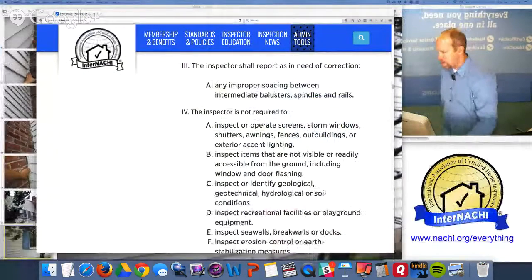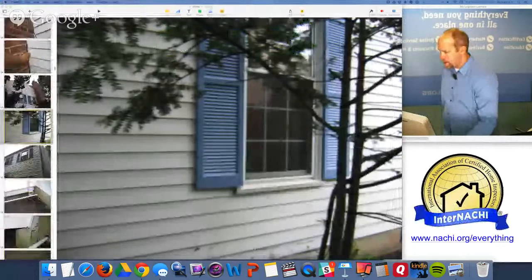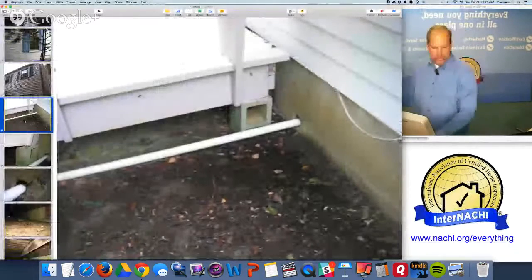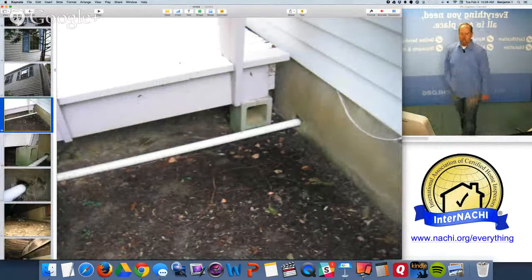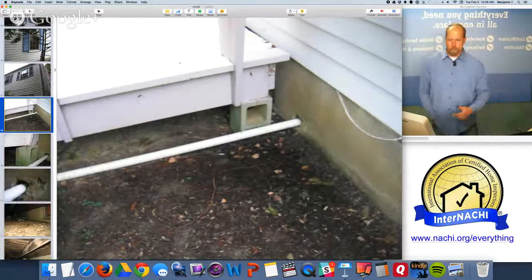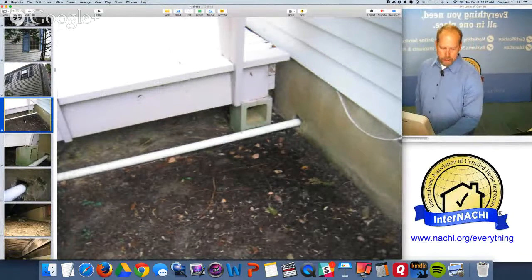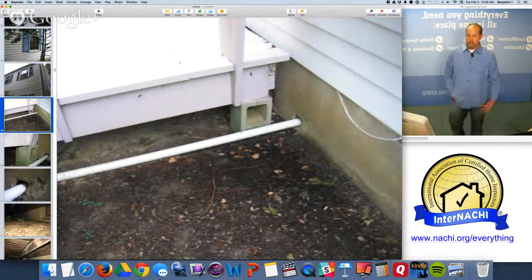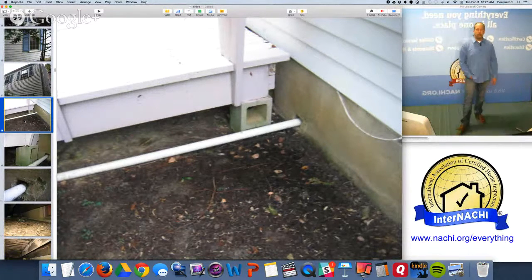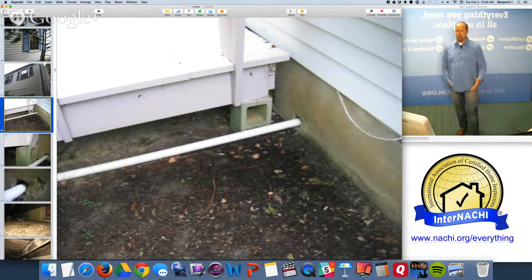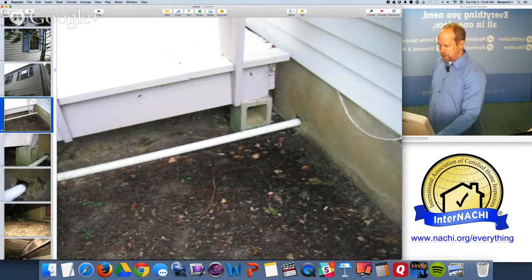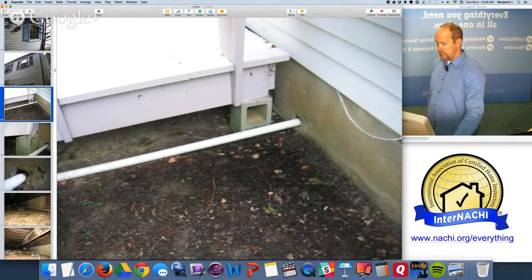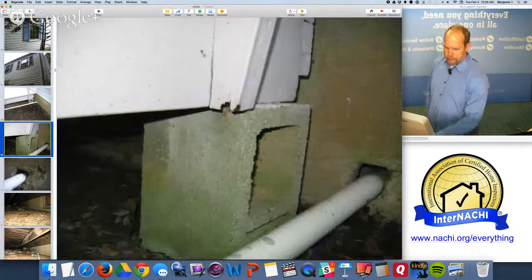All right, back to the exterior. So we have a pipe coming out of the foundation wall, probably just below the band rim joist. It's a sump pump discharge pipe. And sump pumps are used for basements typically, or crawl spaces. This is a northeastern climate. So we have a sump pump in a foundation. This is Pennsylvania. So that pipe is typically a discharge for a sump pump.